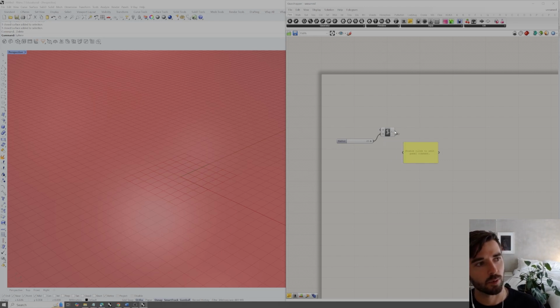So in this case, we'll take the output node from this component and drag it into the input node on the left, always going from left as an input to right as an output, into the panel, and it's telling us that we have an output of an untrimmed surface. If there was some error in this component, not only would we see this battery or component actually show up as either yellow or red, telling us that there's an error or a warning, but we would also see information here possibly saying that no geometry was created at all.